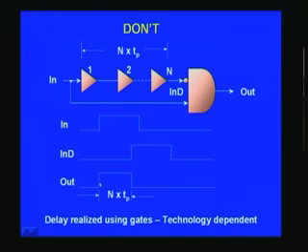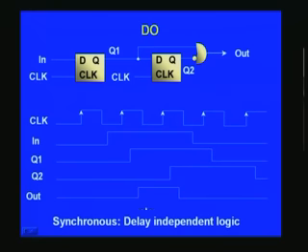So the way out here is, if you are interested in just creating a single pulse as such like this, what you can do is have two flip flops, and input is applied here, and it may appear at any point of time. So let us say it appears here, and there's a clock here, and we are going to reckon the whole thing on positive edge basis.